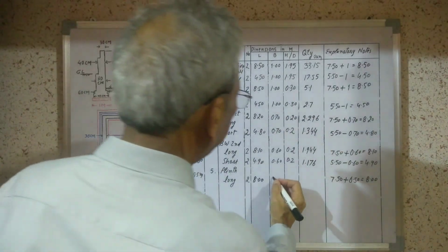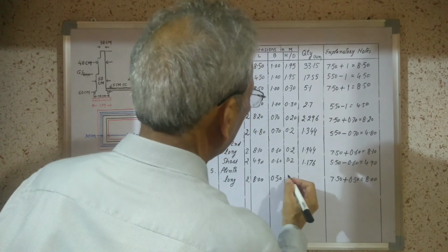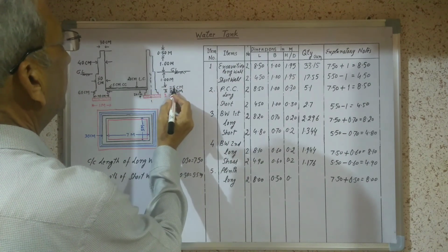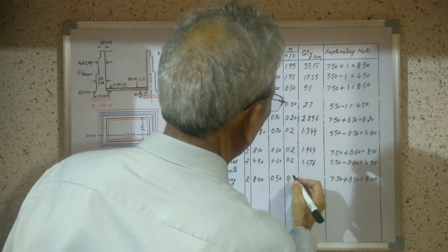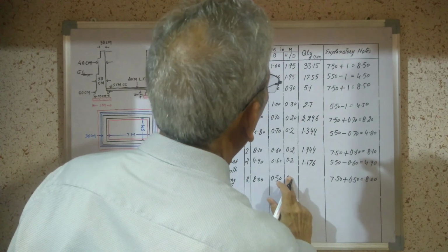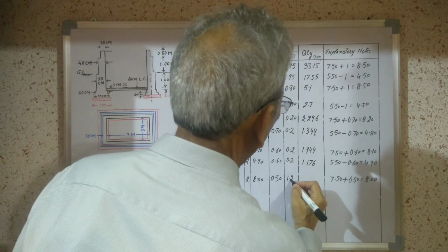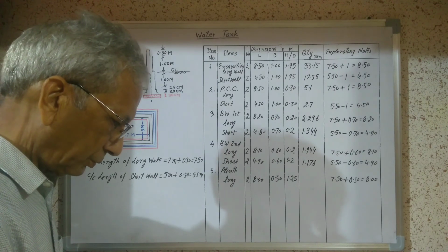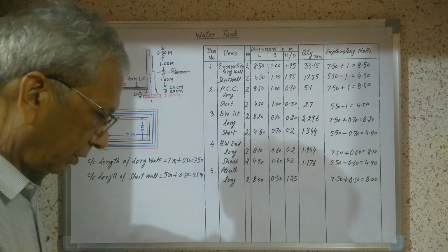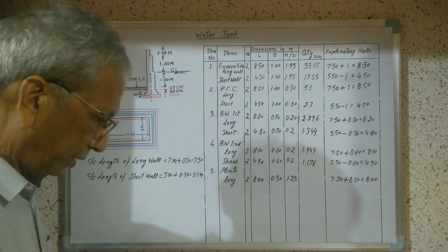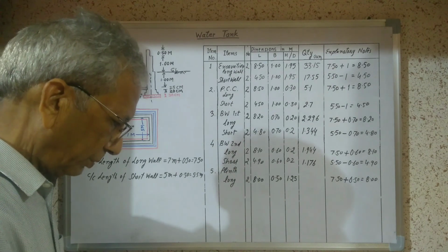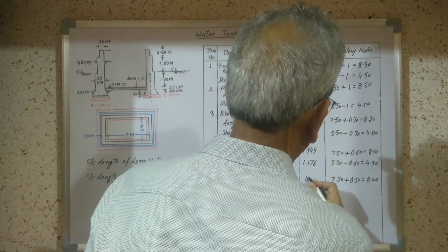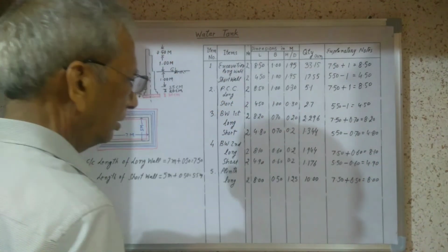Now the width of the plinth is 50 centimeter and height is 1 meter and 25 centimeter, that is 1.25. Now we will do the calculation. 2 number of walls multiplied by 8 multiplied by 0.5 multiplied by 1.25. The result is 10 cubic meter.